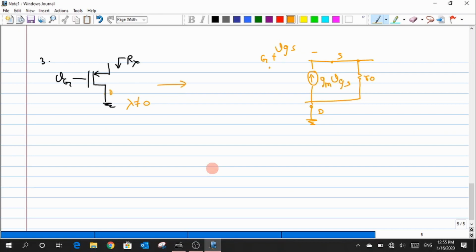So this completes my small signal model. Now to this, I just need to fix a voltage in order to find the output impedance. So that voltage has to be fixed at which terminal? To the source. So I just connect my Vx with plus and minus, and one more thing that I need to do is kill this Vg. So I just connect the gate to the ground.